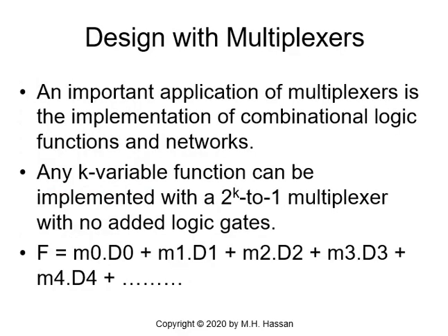Design with multiplexers. An important application of multiplexers is the implementation of combinational logic functions and networks. Any Boolean function, any switching function, set of functions, even very complicated functions could be implemented with multiplexers as modular devices.